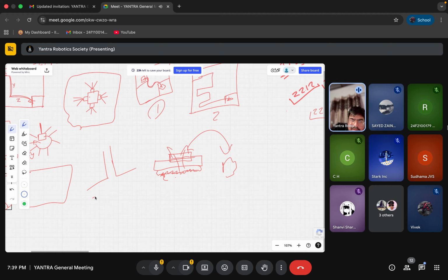Also, for pipe things, we can use soft robotics, some rubbery thing, like a snake. It will swell and go like this, and it can take turns properly, but it is a little bit difficult, to be honest, because it's mostly pneumatic, air based. Mechanically it's also a bit difficult. You just can't expect a wheel or simple pulley system or something like that.